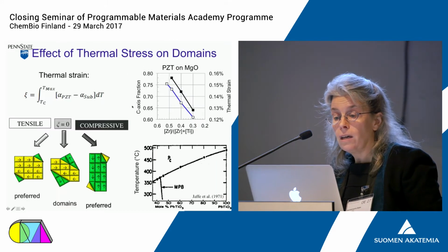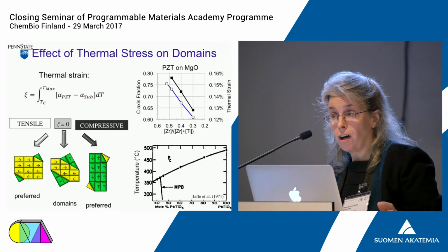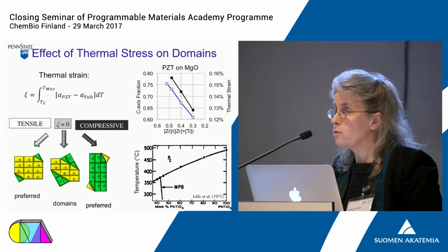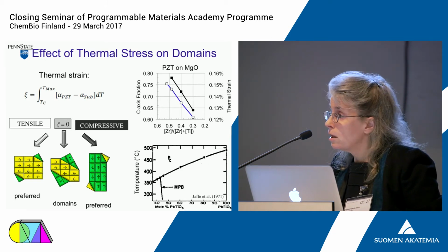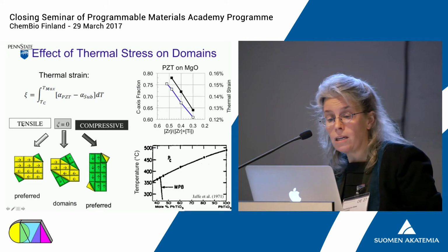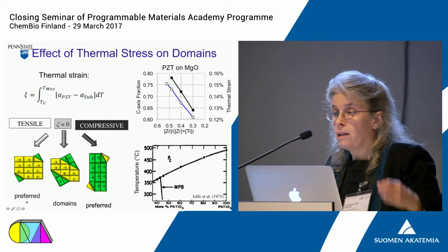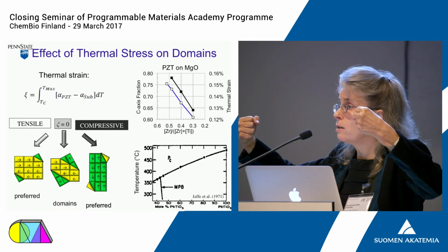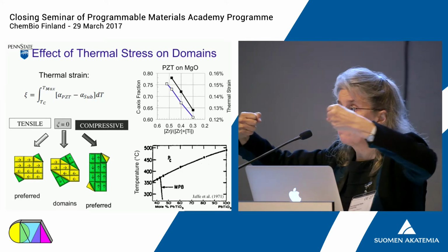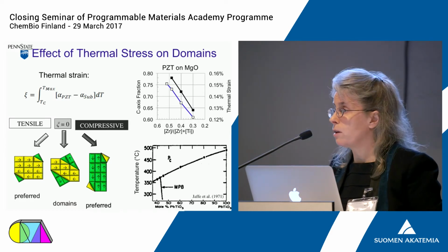predicted value. And the approach that we took, since you need relatively large volumes of piezoelectric, we can't use epitaxial strain here, is to utilize thermal expansion to generate the strains that we need. If you grow a thin film on a substrate with a small thermal expansion coefficient, then we put the film in tensile stress. Remember that the material's elongated parallel to the polarization, so when I put the material in tensile stress, I tend to fold the polarization into the plane.